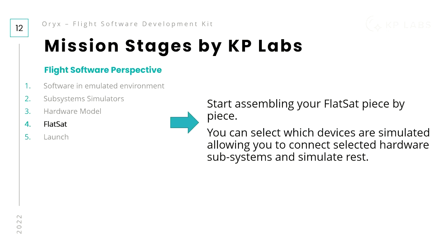You can have a step-by-step verification of each device that you're connected to, and you can verify your simulators if they work correctly as well, which is very important. If you find some discrepancy, you go back, change the simulator to behave the same way, see if you see the same results, and fix it, right? This way, you're not only verifying the flight software, but you're also verifying the test suite.